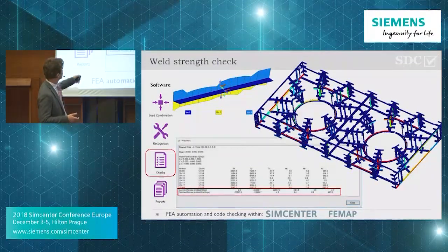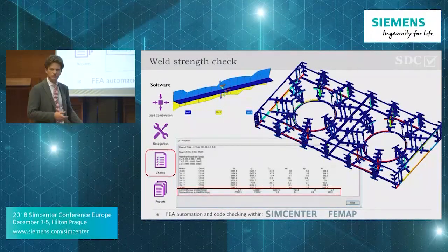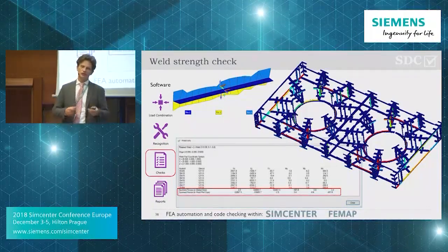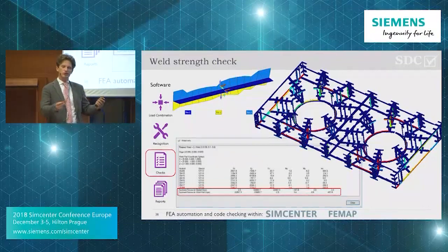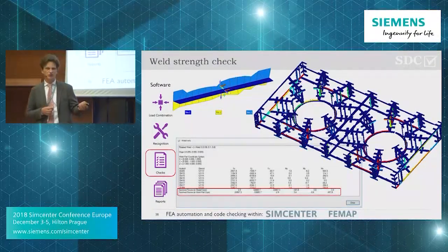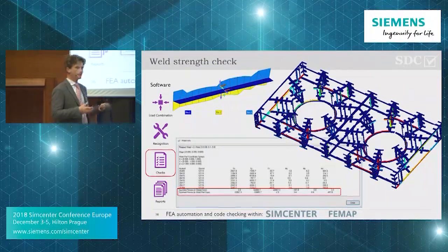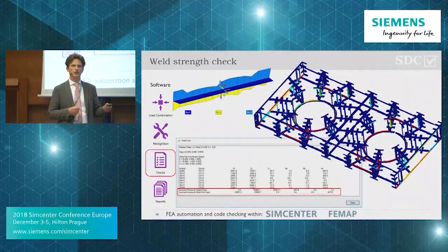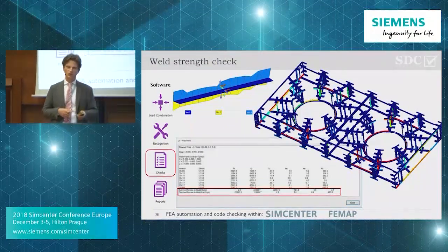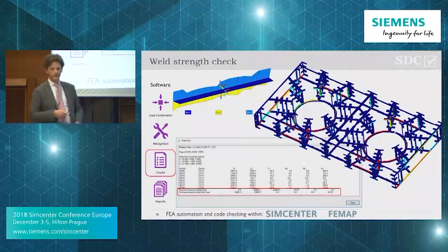So what we do is, for this weld, we sum up for all the elements the typical loads, and then sum that all up in the global coordinate system, and then we change that into the weld coordinate system, because there you can compare directly if your weld capacity or weld resistance is comparable to the real value. And then instead of having stresses and stress overshoots at the tips, you only have a single result. The weld either is okay or it's not. So you can see here, per weld I have a single value.